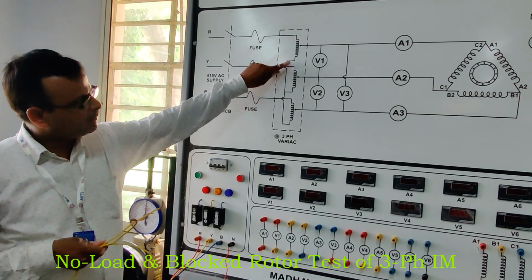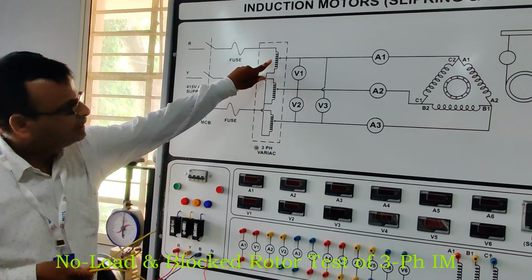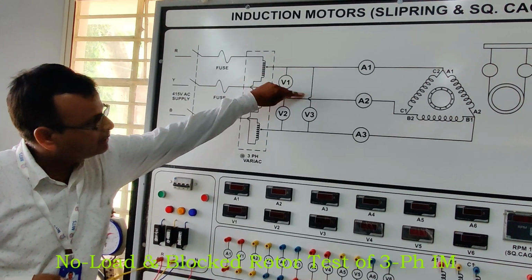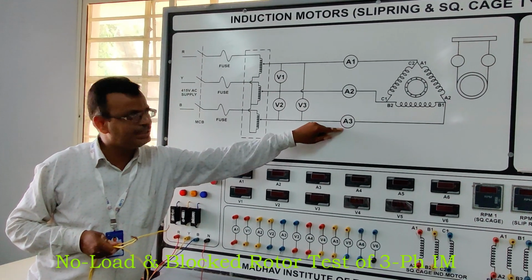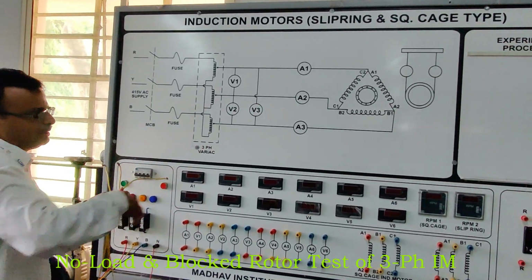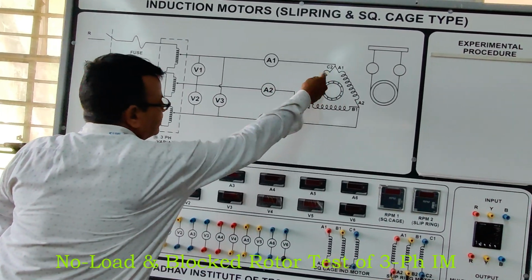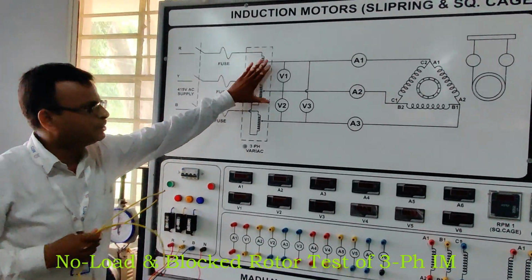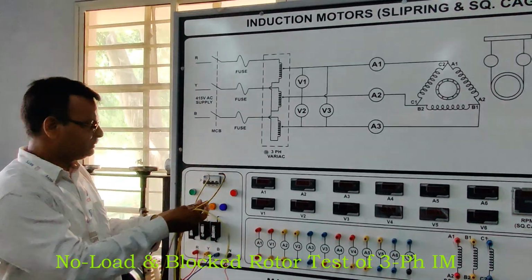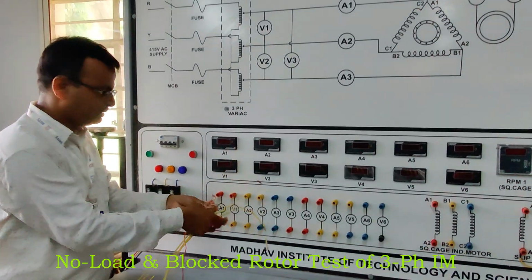See that these are the auto transformer terminals. There are 3 line terminals, 1, 2, 3. In these 3 lines, the 3 ammeters are connected in series, and these terminals go to the 3-phase squirrel cage induction motor. So first of all, we connect this portion of the circuit, and this one is the ammeter here in series like this.